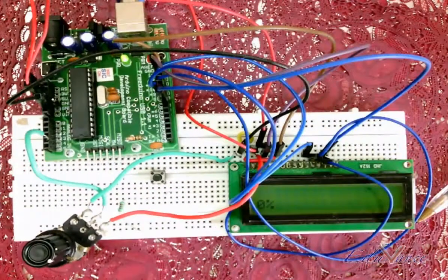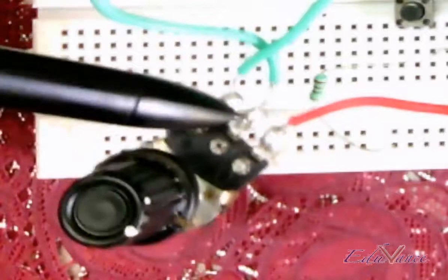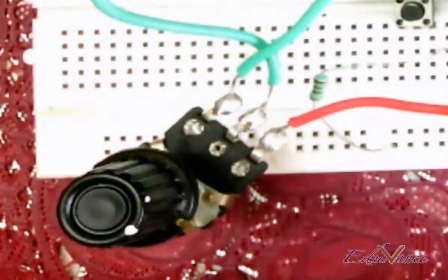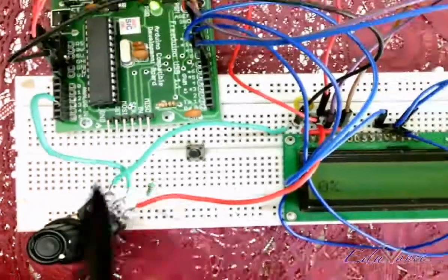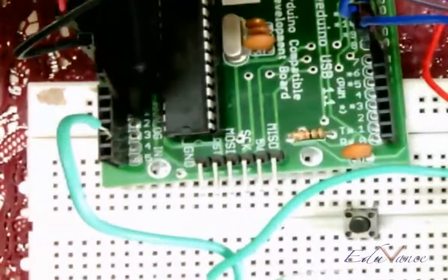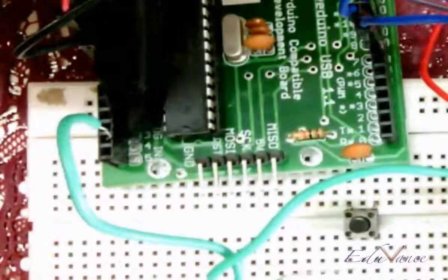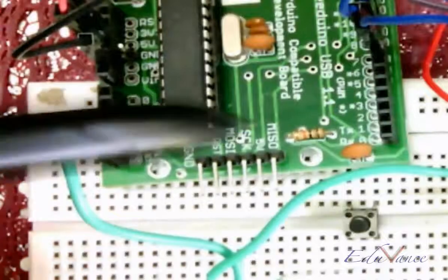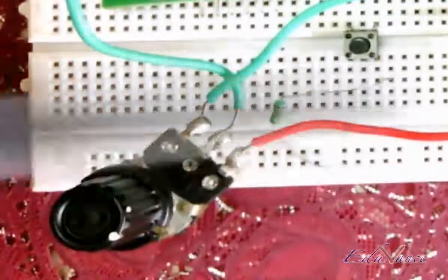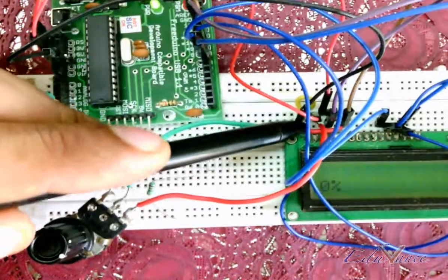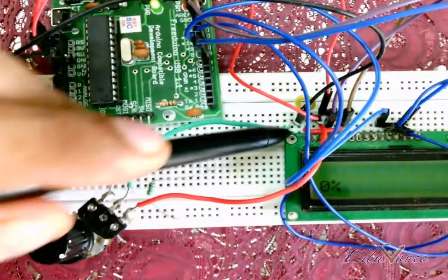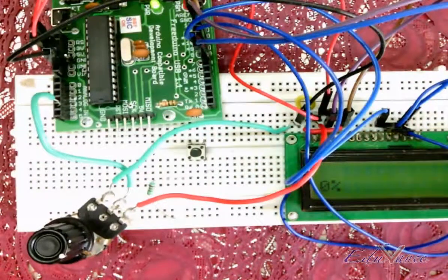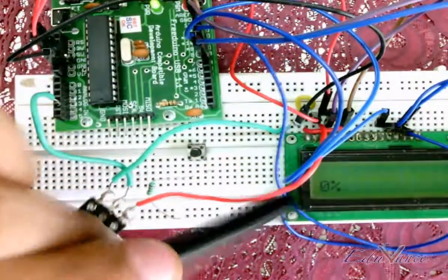Now on the board, as you see, this is the potentiometer which I will rotate. I have connected the center terminal of my potentiometer to A4, which is the analog in 4 terminal. I have connected VDD, which is this terminal, to the VDD of my LCD. So the VDD is connected here, and then the ground is connected to the ground of my LCD. So I've just used these connections. These connections are all the same from your LCD lab.